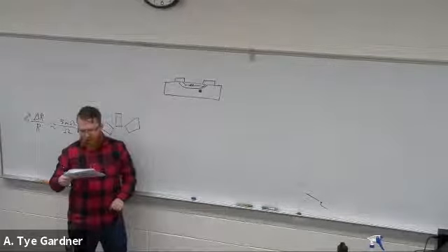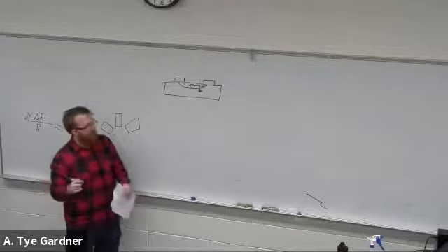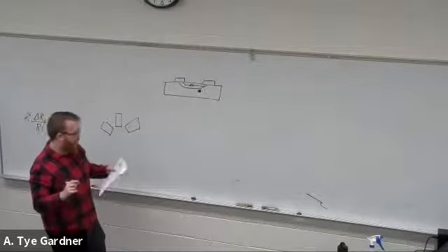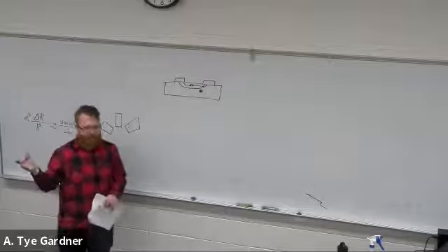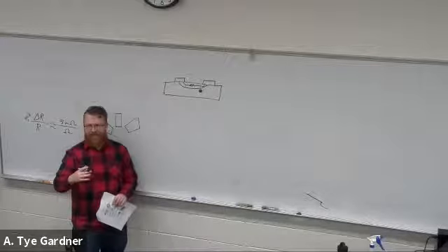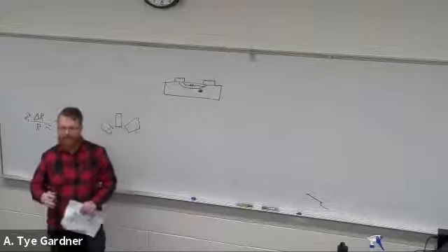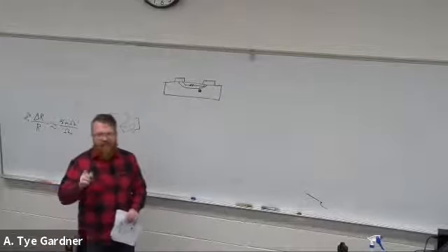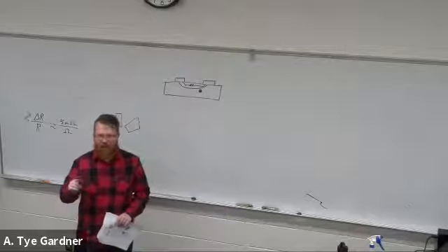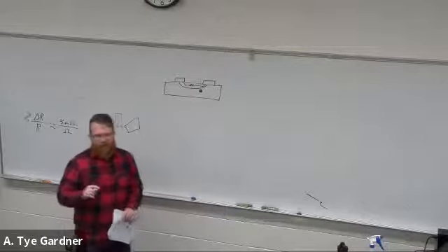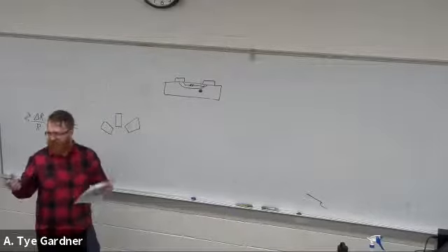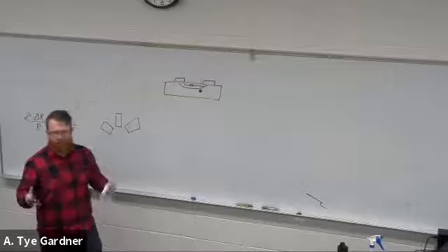What's super nice is that silicon, for one, can have gauge factors up to about 150. And this is as of like 2008 or so, so I don't know how much better they've gotten since then. But the cool part is they can actually have negative gauge factors. They can go the other direction, right? And it's just how you dope it. That's all that you need to change in order to change the gauge factor. You can't have a negative gauge factor with a passive wire.